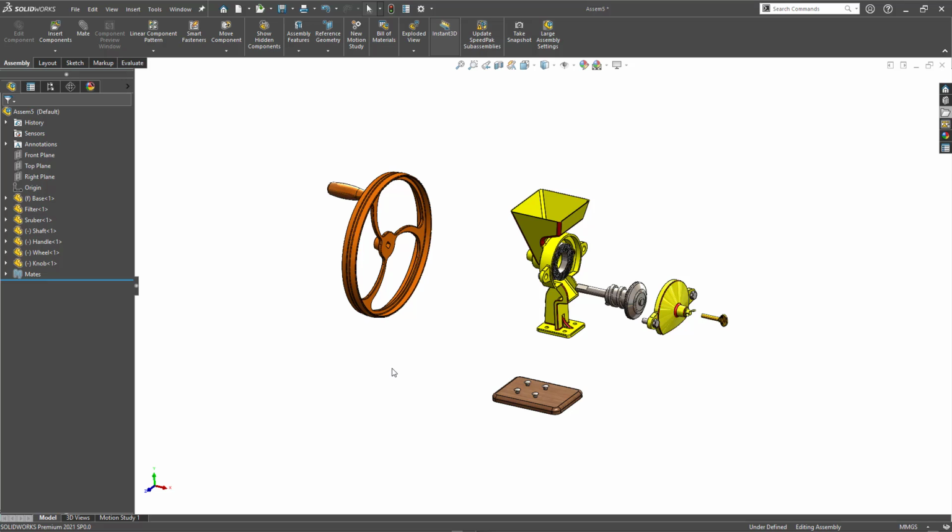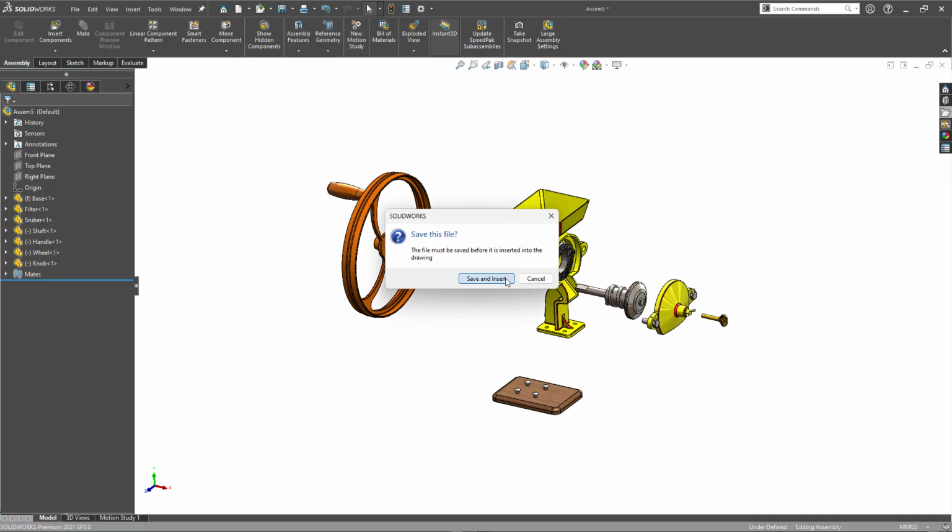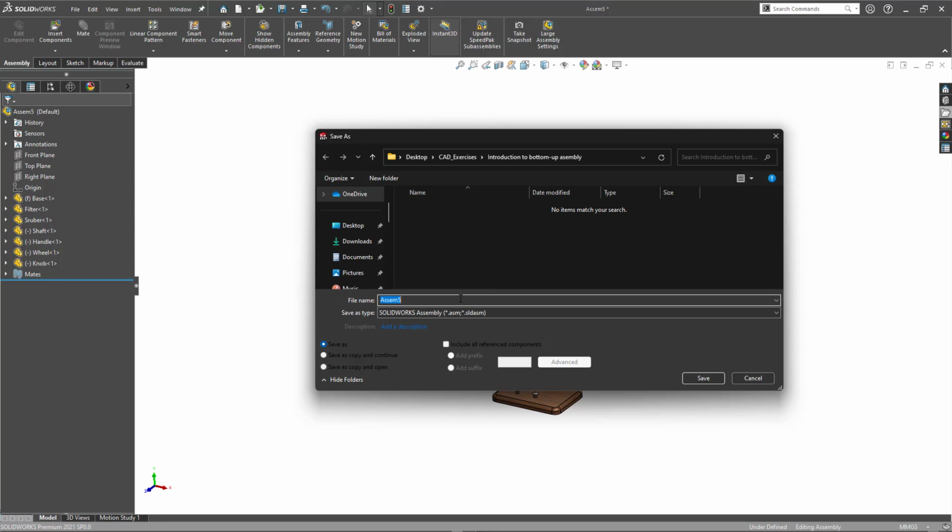Now once you have the exploded view, what do we do next? We can create the bill of material and the assembly drafting for this. To do that, you can go to the File menu. There is an option called make drawing from part or assembly. You can just select this. Before that, I would like to save the part. I would like to save it as mill assembly. You can just save this.